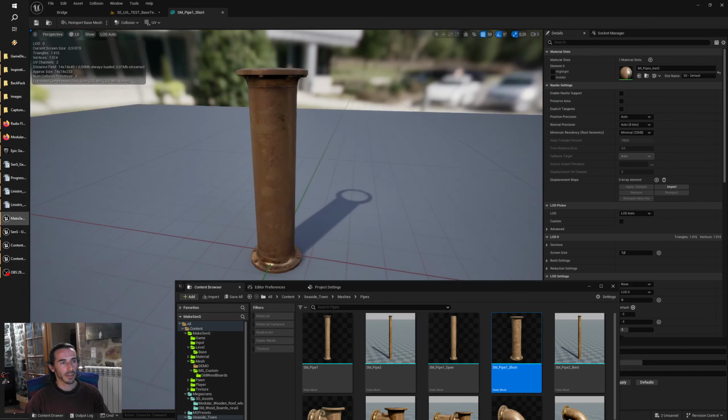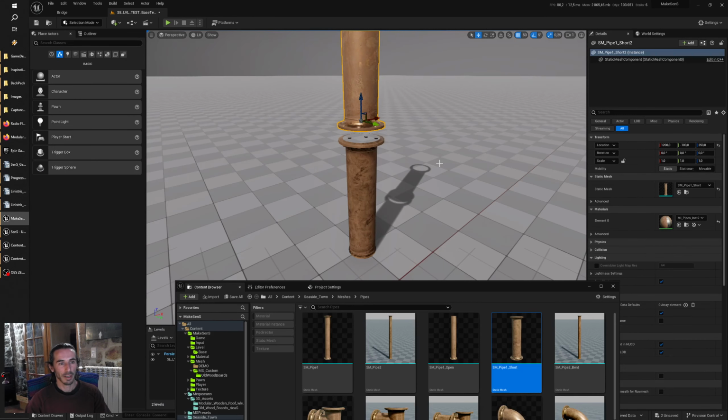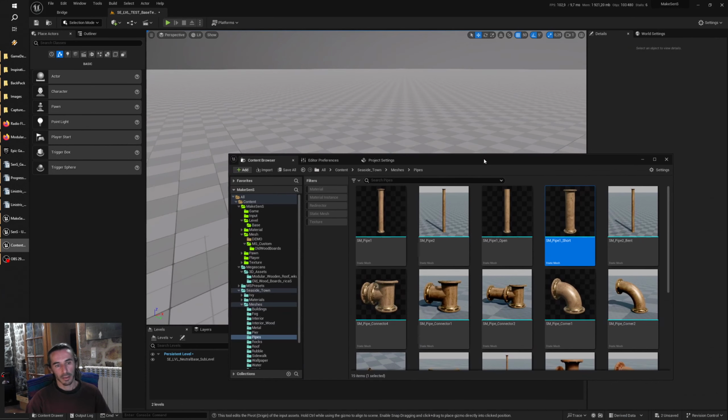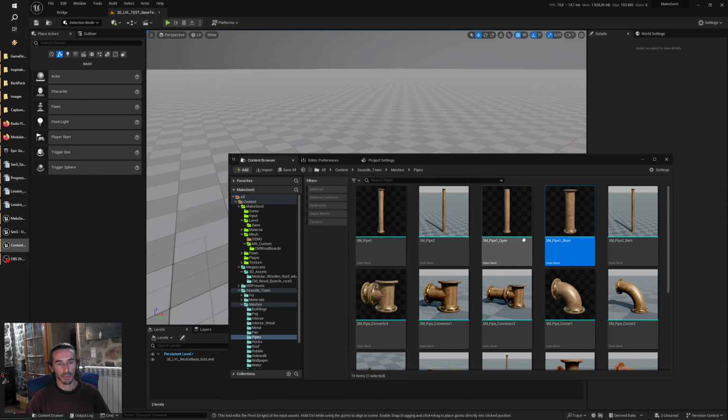It's 233 centimeters high, which is not a round number, which is problematic when you want modules, bricks like Lego bricks that you can place easily. What you have to do first is to duplicate your models. You will prefer to keep the original models just in case you need them for whatever reason.